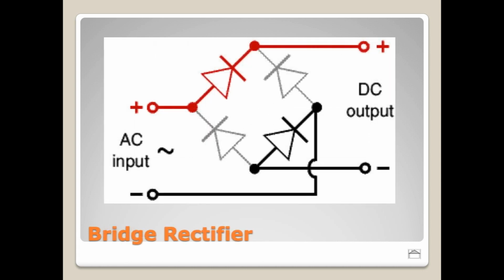But with our bridge rectifier, we are doing full wave rectification, not half wave rectification, but full wave. We're not wasting any of this stuff here. We want to make sure that we get every single chunk of that. And then ultimately, we're going to end up smoothing this out into a nice straight line using some other components as well. So this is really step number 2 in your traditional power supply. First, we're going to have the transformer, and then that transformer feeds into your bridge rectifier.